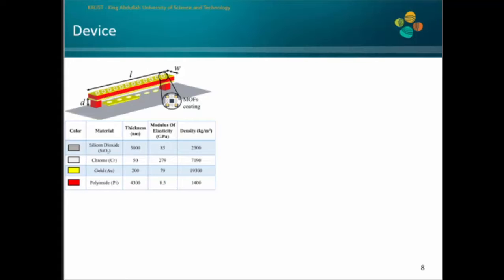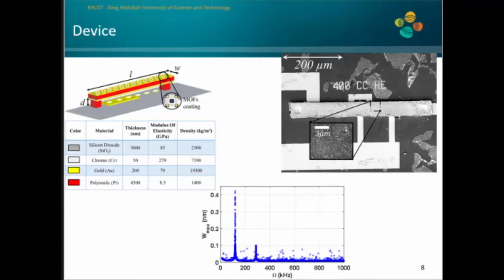Now, we perforated the lower electrode here to provide an air path for the trapped air molecules to escape, so as to reduce the effect of squeeze film damping, and hence we can see a moderate quality factor when we operate this resonator at atmospheric pressure, which is really an essential requirement for any gas sensing application, that you need to operate the resonator at atmospheric pressure, not inside a vacuum chamber or controlled pressure condition.